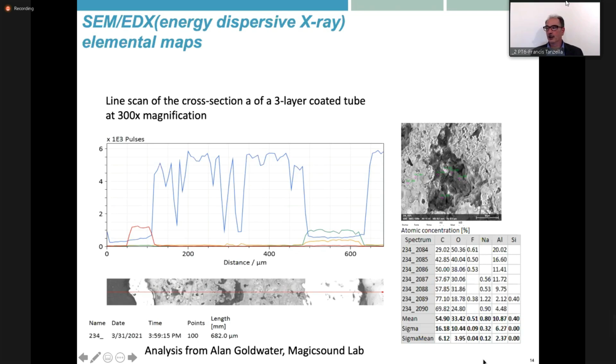It is interesting to note that the aluminum oxide ratio is relatively constant, even though there are several other impurities sitting on top of it. The alumina seems unchanged during its run. The carbon concentration seen is from the machine background or from epoxy that moved into the voids during polishing.